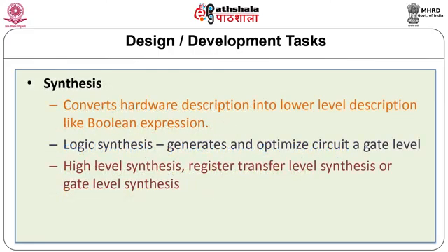Synthesis. Another design task to be performed is the synthesis. In the synthesis process, the hardware description is converted into a lower level description, for example, a logic or Boolean expression. Logic synthesis is mainly focused on generation and optimization of a circuit at logic gate level.